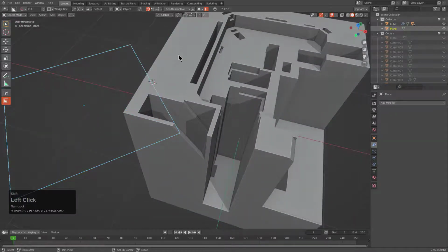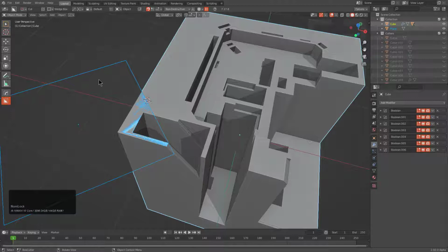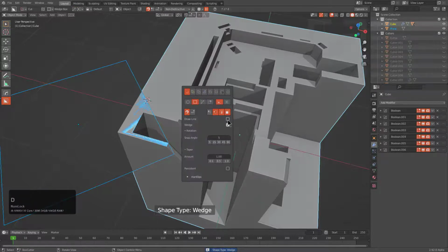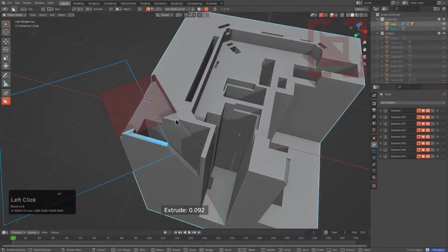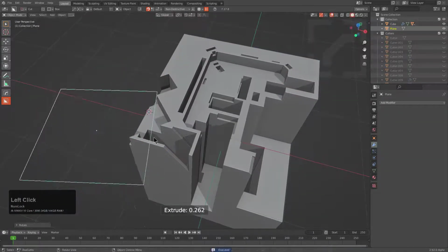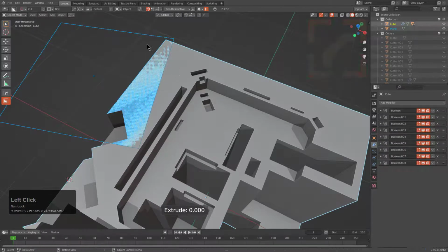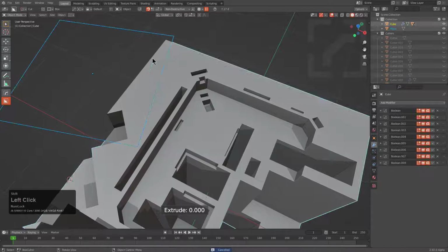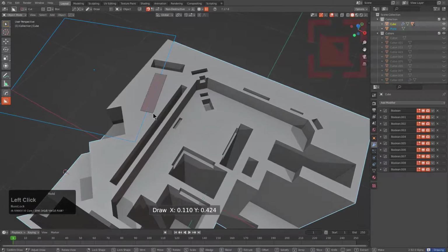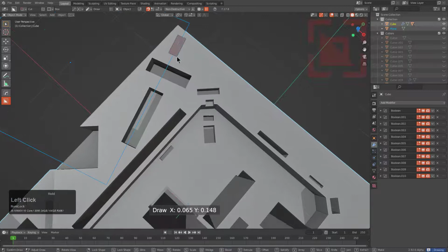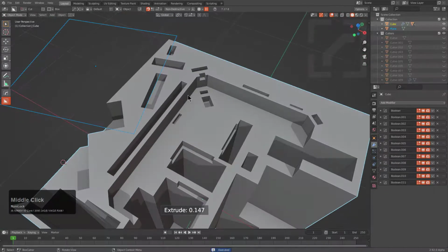So here I have the plane selected, and then I have the object selected. And let's actually change this to be just regular old box instead of wedge box. So we could actually press Control D and bring up our helper to turn off wedge. And here we are actually using this plane to orient our drawing. So there's multiple ways that you can actually override some of the rules that we have set with BoxCutter. We want to give users as many choices as possible whenever it came to such things. So in the event that you ever need to just override it using a custom shape, just know that you can do that using the power of active only.